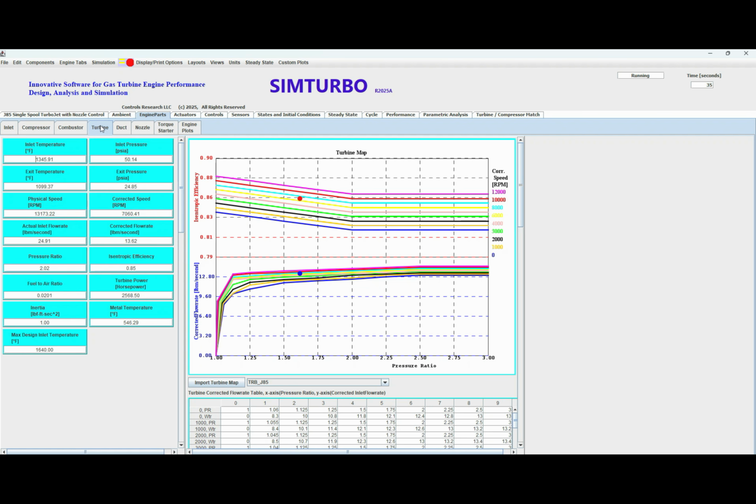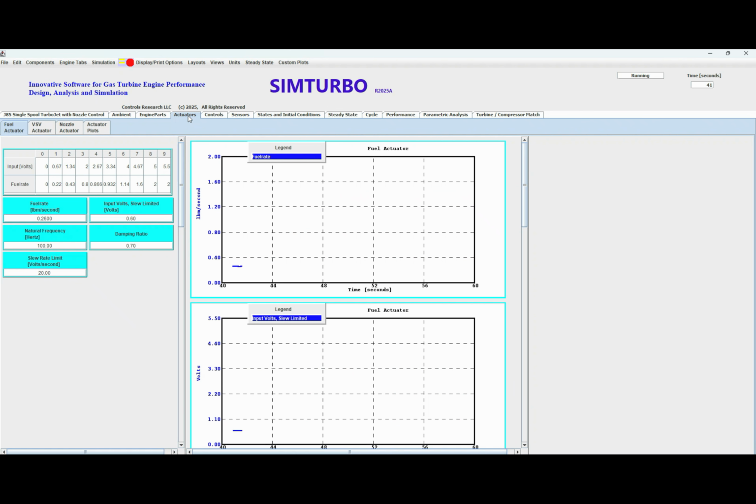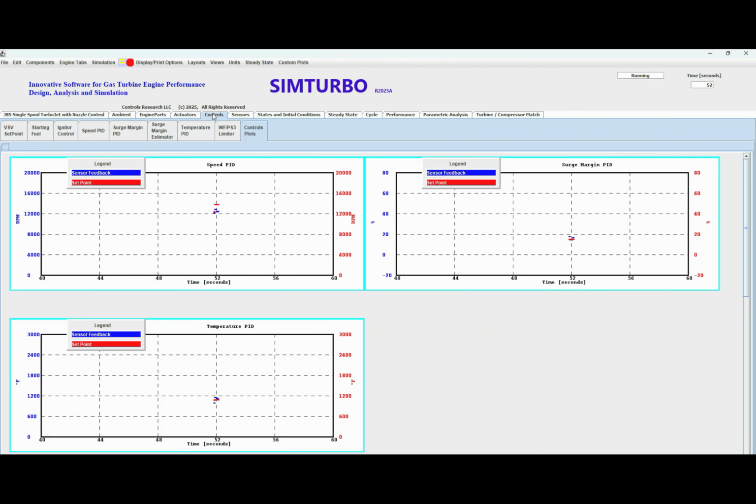The software uses high-speed, zero-dimensional (0D), or sometimes one-dimensional (1D), lumped parameter models. Component maps are key here. And that speed is absolutely vital for dynamic and transient analysis. Think throttle slams, quick power shifts, and probably most importantly, validating the FADEC's response to those events. It makes it perfect for rapid software-in-the-loop testing. SIL testing. Right, SIL.